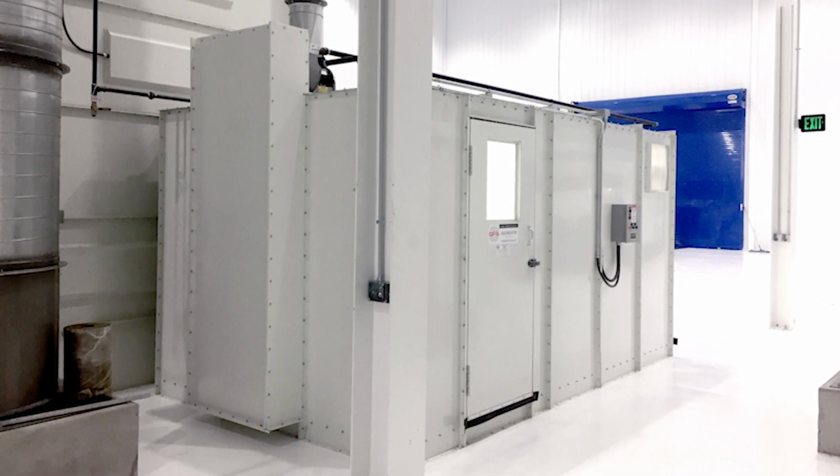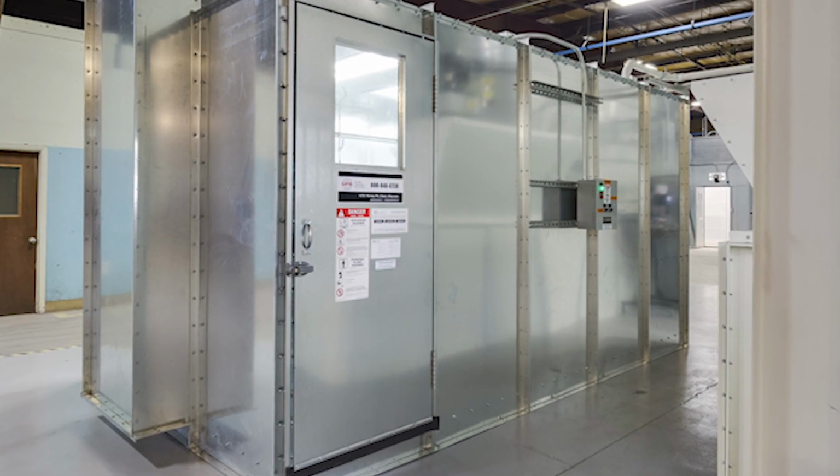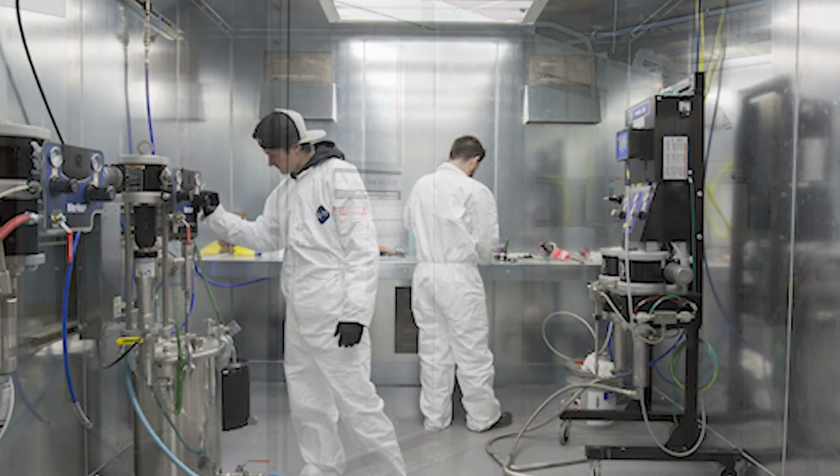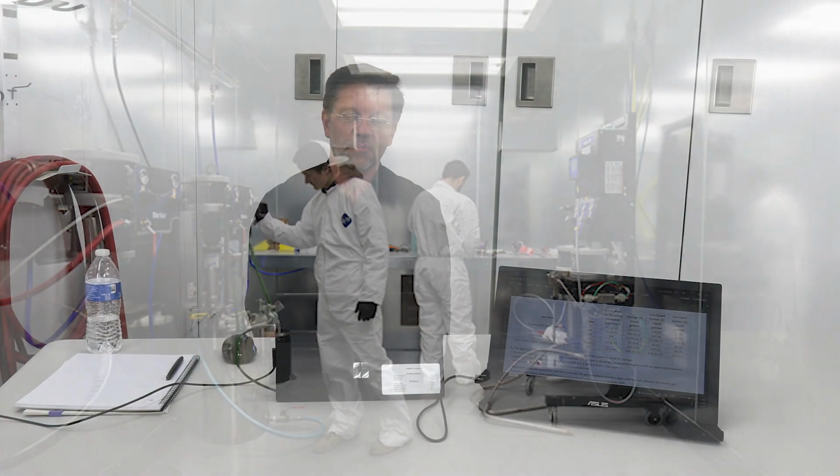If located more than 6 feet from a spray booth, the amount of liquid in a mix room shall not exceed 2 gallons per square foot, regardless of the class of liquids present. If located adjacent to or within 6 feet from a spray booth, the combined amount of liquids in a mix room and the adjacent spray booth shall not exceed 120 gallons or 2 gallons per square foot of the mix room area, whichever is less.